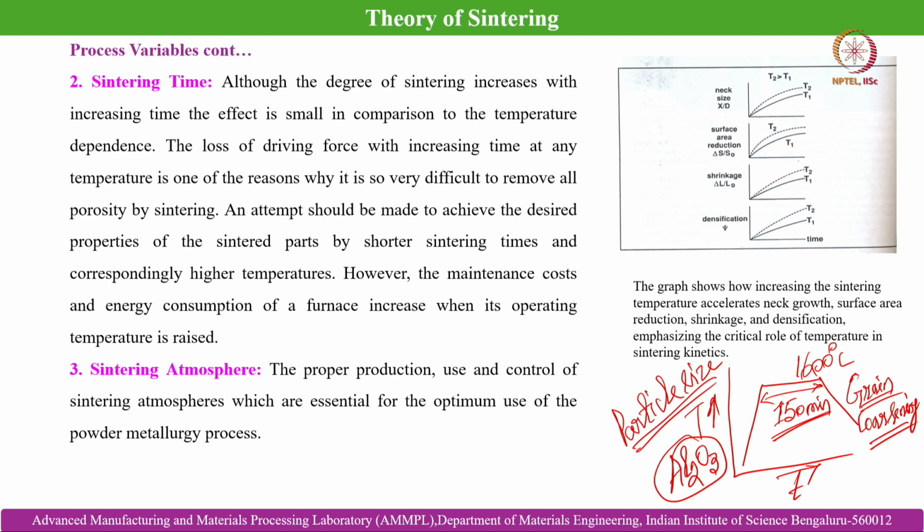If the particle size is constant, then beyond a particular optimum sintering time we can experience grain coarsening as well as pore coarsening. These are the two things we can experience if we go for a prolonged sintering time. That is why it is very important to optimize the sintering time. If we try to decrease the sintering time by increasing the temperature, then it pushes the equipment to the limit, because higher temperature means it needs a higher energy source, and that may not be economical at all.